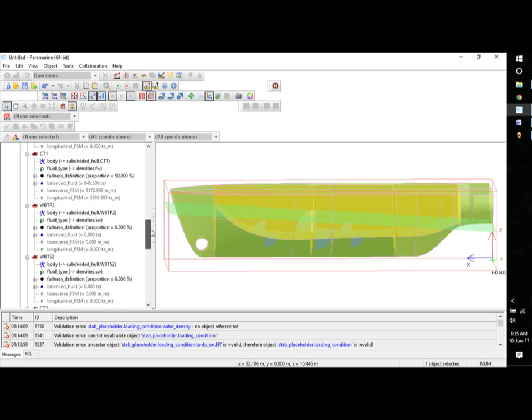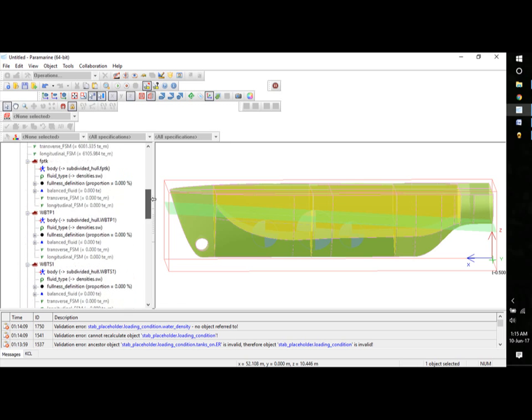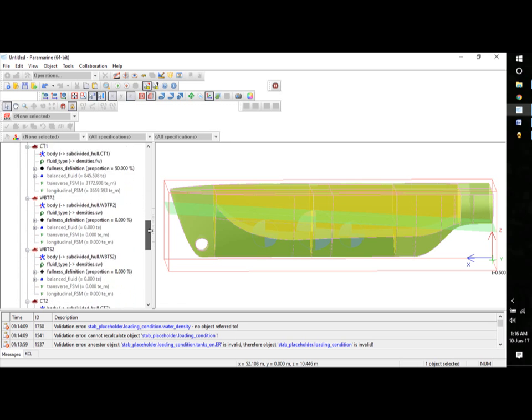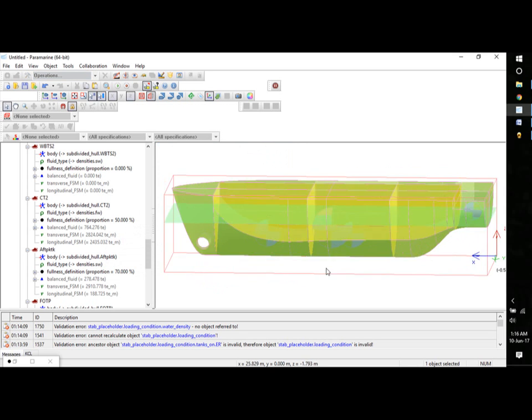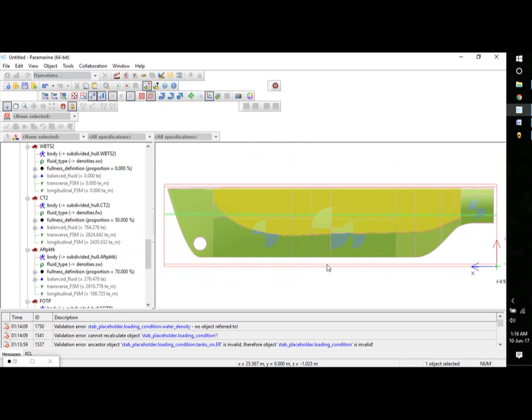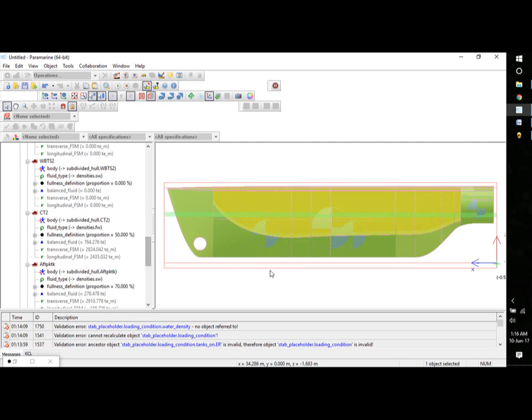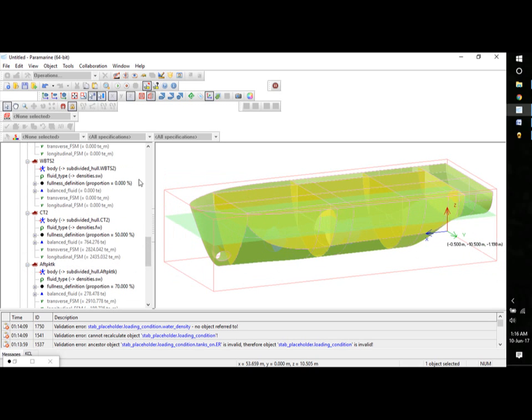Let's say I'll put the aft peak tank. So what is the aft peak tank? I'll fill that to around, let's say, 70%. Now you're almost there, but again you have a trim by the forward. That's okay. You will take some water in the number 1 ballast tanks.